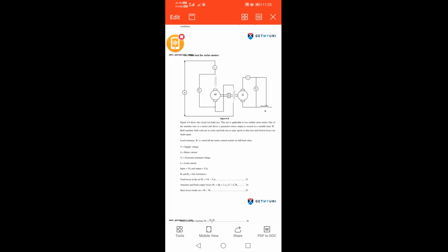Motor voltage, right. So motor back EMF. Why? Because it is connected across that series winding and armature winding, right? In the armature winding, the available EMF is the back EMF. So here voltmeter V1 measures the back EMF available on the motor armature winding. At the same time, V2 is connected across the armature winding. That's why V2 measures the generated voltage available in the armature winding.